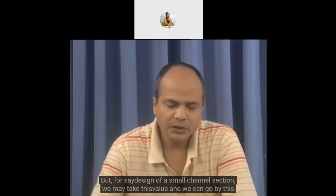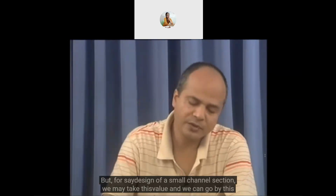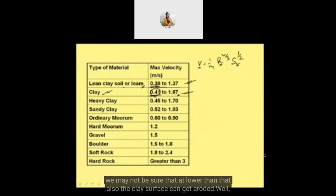But for, say, the design of a small channel section, we may take this value and go by this permissible value. When we are not sure about the maximum value, we should go for the minimum value suggested as the maximum velocity, because the range can be from 0.41 to 1.67 for clay, say. So if it is clay and we do not have much idea, we should be conservative in our design and use 0.41 meter per second as the value. Because if we take a higher value, we may not be sure that the clay surface will not get eroded even at lower than that.